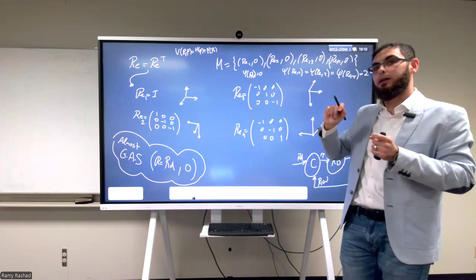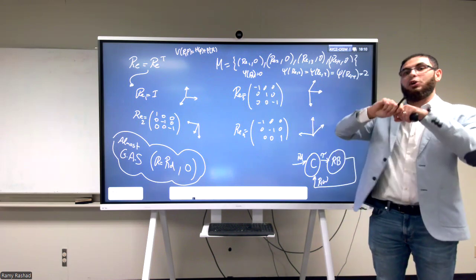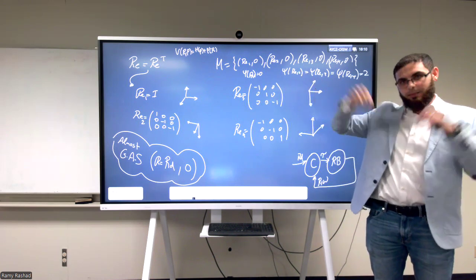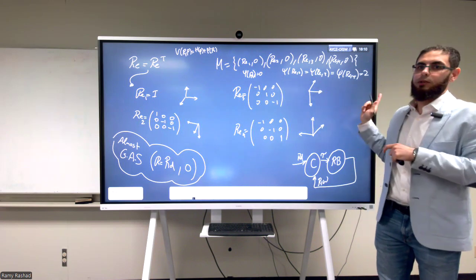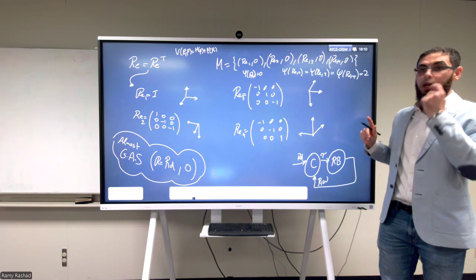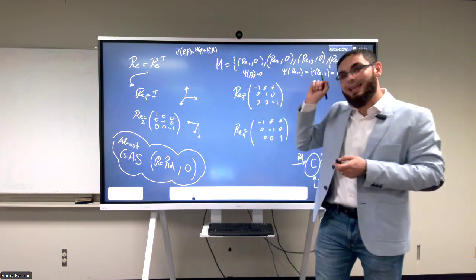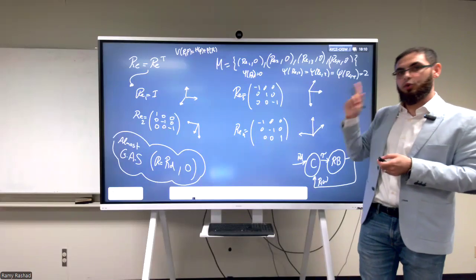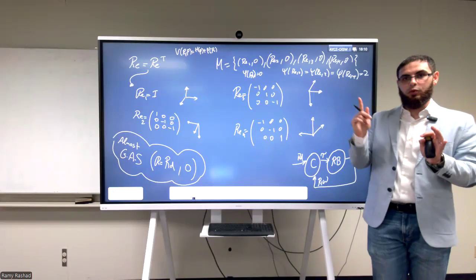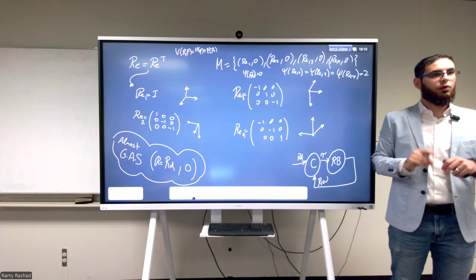And this is why we call it almost globally asymptotically stable, which means that if I start anywhere in the state space, I am going to go to the equilibrium point, except for these 3 points. Almost, because to really say global asymptotic stability means you don't have any other equilibrium points, and actually you have only one. Other questions?